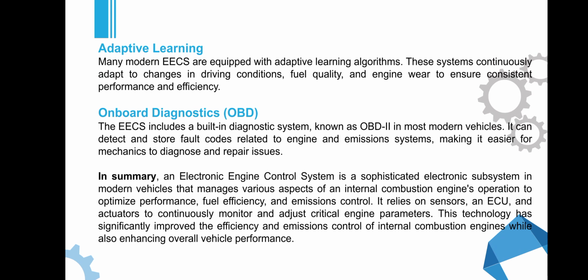Adaptive learning. Many modern EECS are equipped with adaptive learning algorithms. These systems continuously adapt to changes in driving conditions, fuel quality, and engine wear to ensure consistent performance and efficiency. Onboard diagnostics. The EECS includes a built-in diagnostic system known as OBD-II in most modern vehicles. It can detect and store fault codes related to engine and emission systems, making it easier for mechanics to diagnose and repair issues.